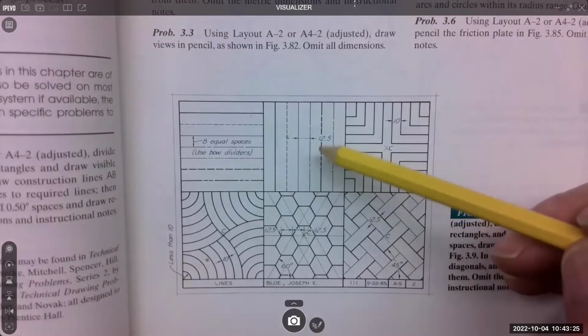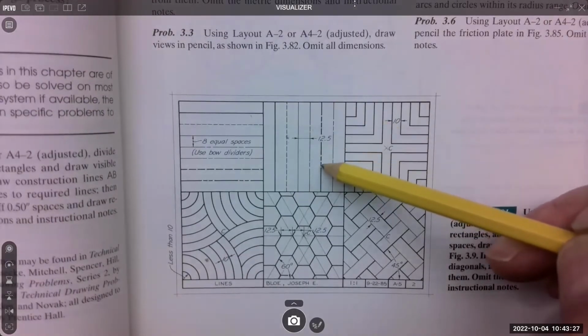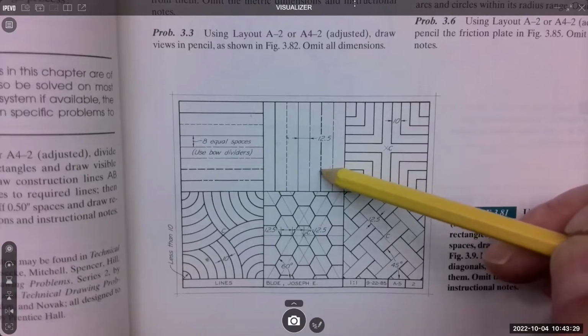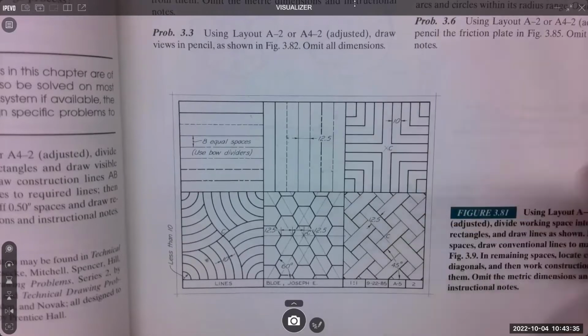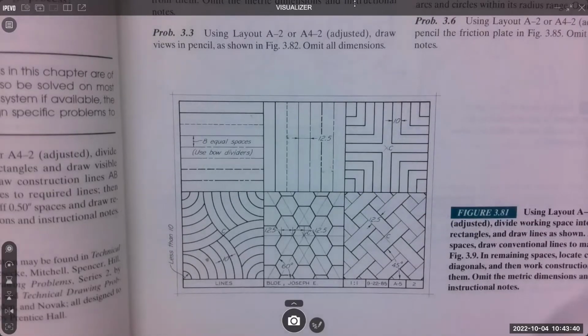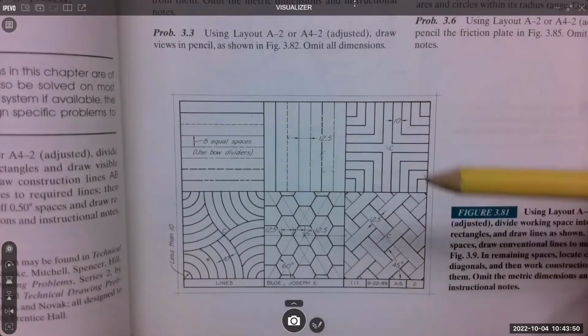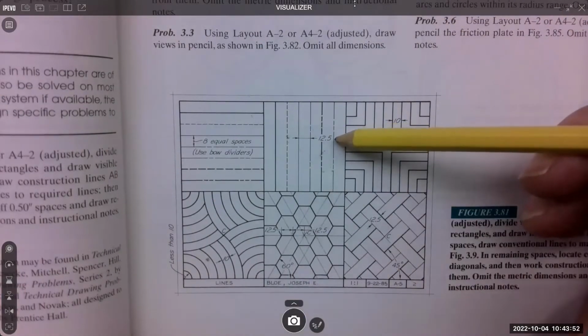All right. And then there's this line, which is called a phantom line. It's got 2 dashes. It is a cutting plane line. So when we do sections, we have to represent where we're cutting the object, because then we kind of peel it open and look at the guts. So that's for an object that has a lot of hidden geometry. We're going to do these sections or cuts. So that's a phantom line. And then this is a thin phantom line.